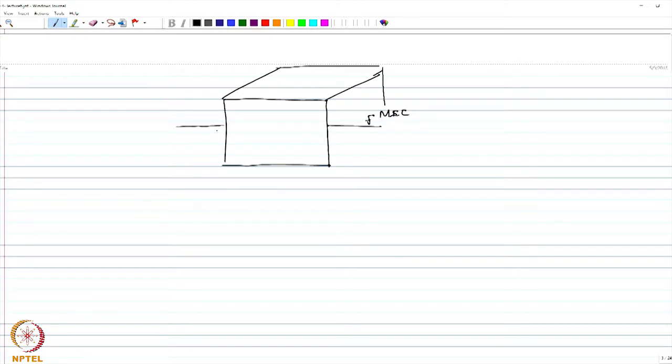It consists of columns and pontoons, as I am drawing on the sketch now. The mean sea level or still water level is marked horizontal as you see there. I am trying to draw a 3D figure of a rectangular TLP which is integrated by different modules of columns and beams. Now, the structure is partially immersed in water, therefore, it raises buoyancy, which is an upward force referred to as Fb. The platform will also have a weight which is referred to as W. W and Fb are essentially coplanar, collinear, and for a symmetric design they are concurrent.